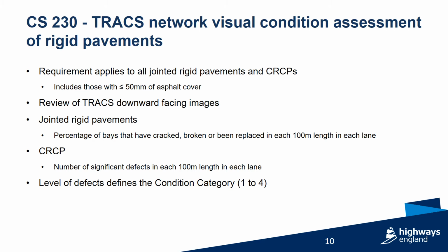The standard sets out the specific range of the defects for each rigid pavement type. These are grouped into 4 condition categories. The results of the assessment shall be uploaded into the HAPMS pavement management system.